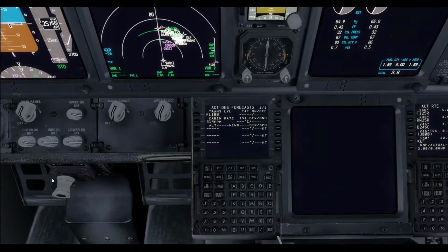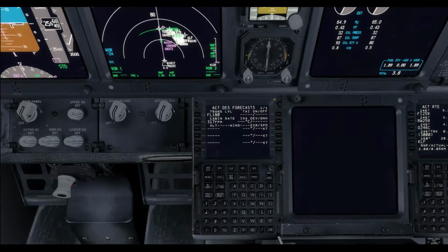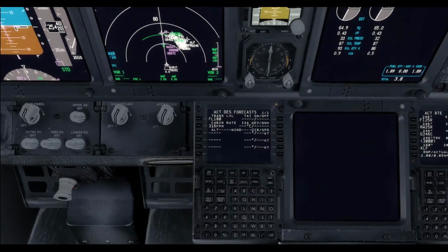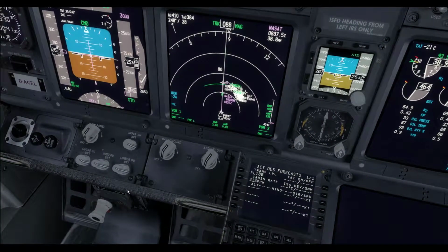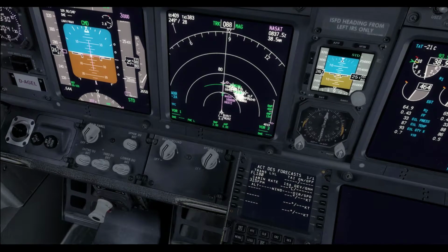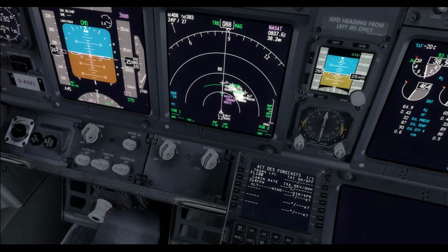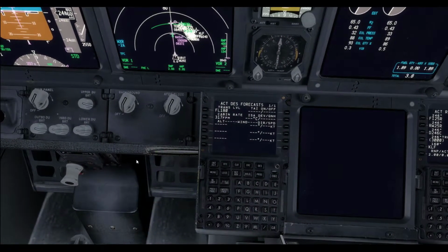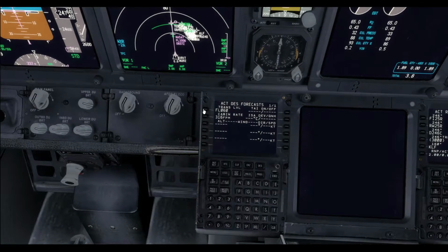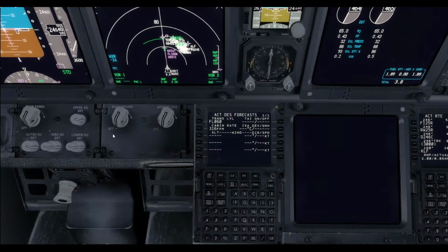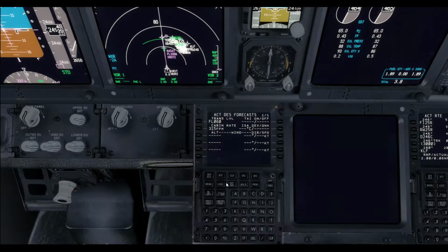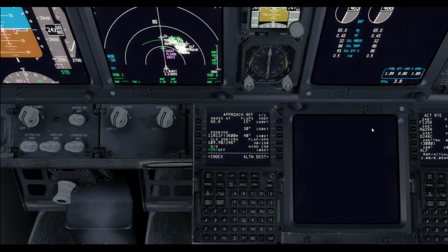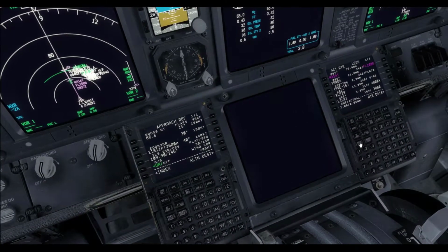What you do is... is the page gonna load? No. You put in your transition altitude, you put in the QNH, and it'll give you the transition level. In this case, I can do that by myself. I think it should be flight level 60. Transition altitude is 5,000 feet. So always check back on the init ref page in case the speeds have changed, but they haven't, I think.